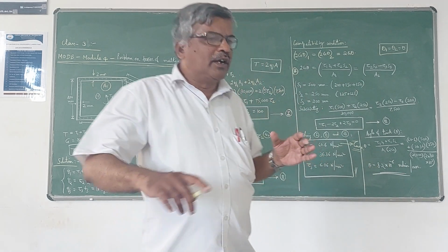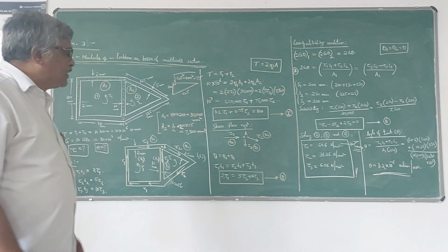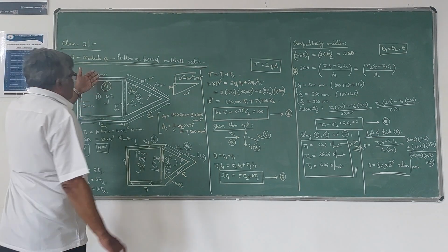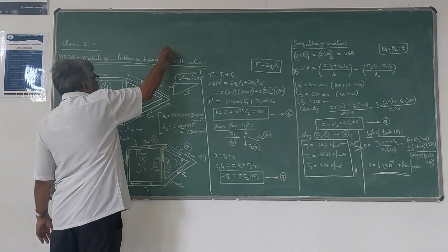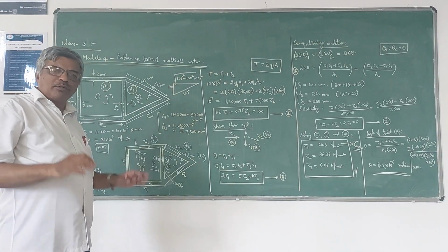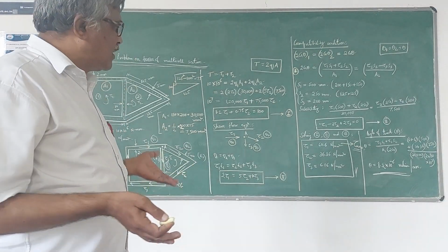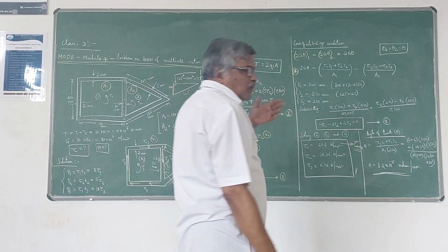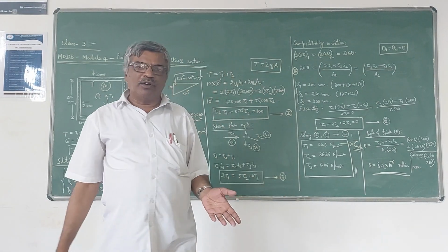So that angle of twist is represented as radian per unit length or millimeter. If you want the total angle of twist, and the length of the section is given, you have to multiply that length in millimeters by this value of theta to get the total angle of twist.